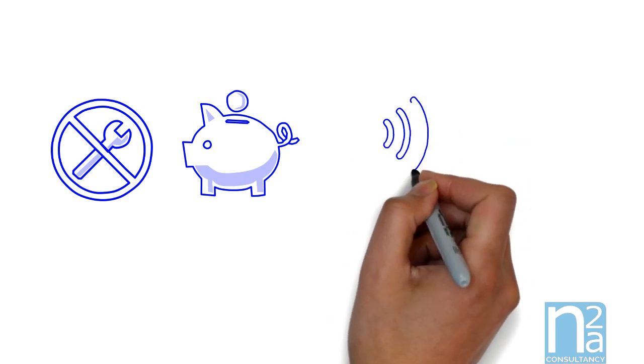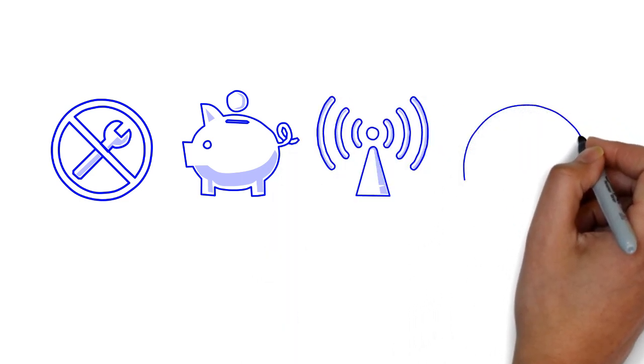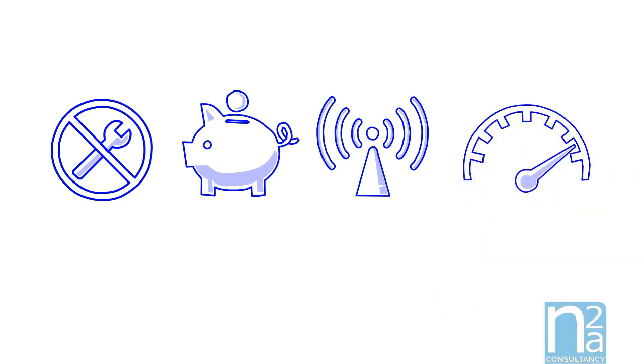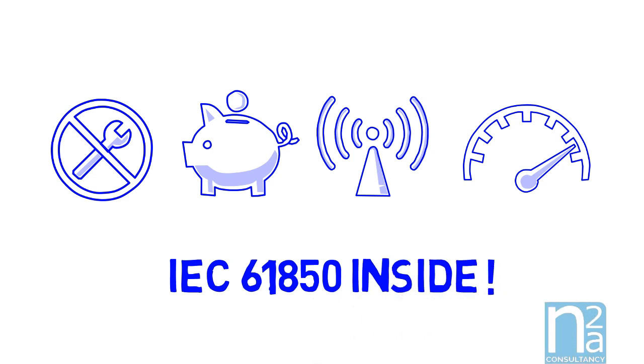EMC and EMI sensitivity is dramatically reduced. Messages are delivered quicker than with wire connection, 4 milliseconds compared to at least 10 milliseconds. But to work correctly, IEDs should be designed for it, not converted to it.